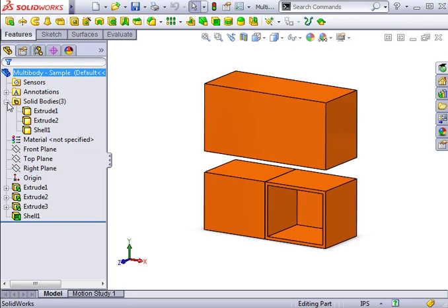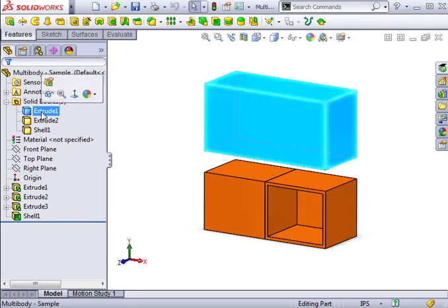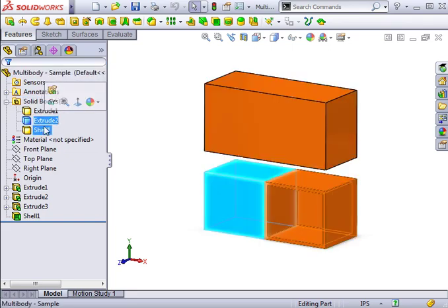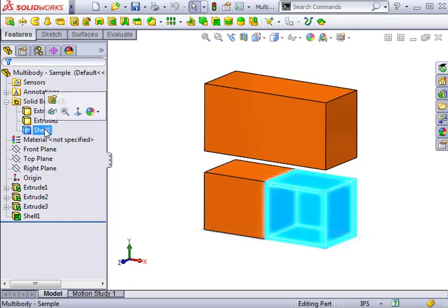From here, you can make selections of bodies for a variety of purposes, including changing their color, combining them, deleting them, hiding them, and so on. By clicking on each of the bodies in the folder, you can see the lower disjoint body is actually made up of two bodies. The bodies are touching, and although you can see an edge where they meet, there is no space between them. They form a continuous solid. However, because of the way they were created, SolidWorks understands them to be individual bodies.